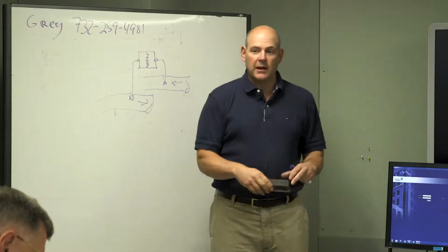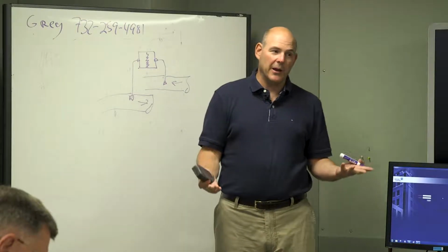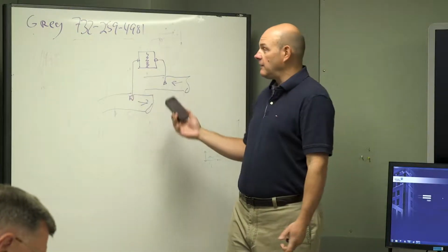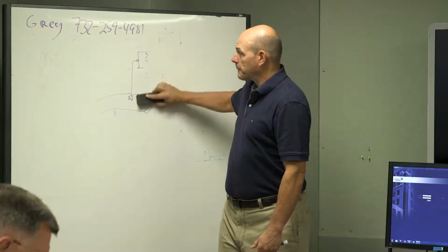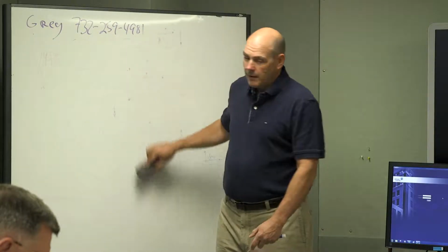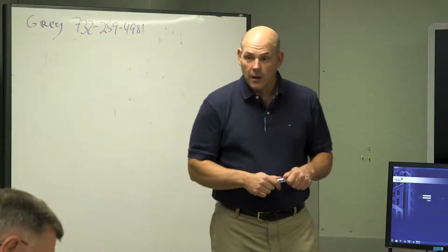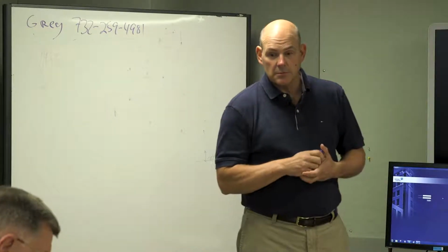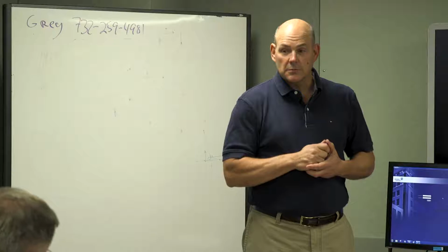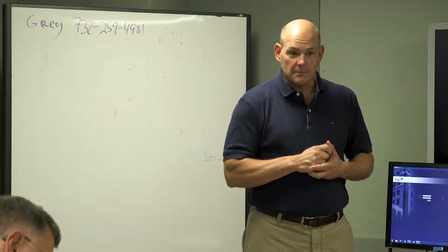And it also keeps your efficiency up in the plant. If you keep everything clean, your efficiency is going to be better. So that's that point. And again, if differential pressure goes down, this might be a problem with the pump, strainer, something like that. Okay.